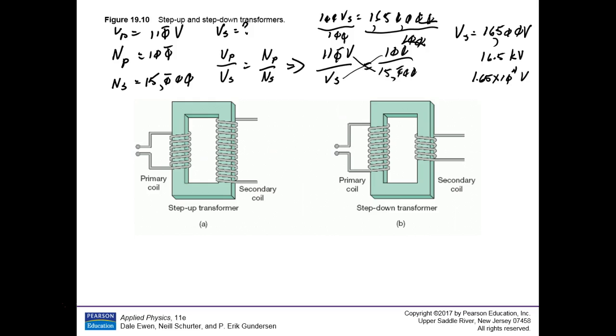Copper losses. These result from resistance in the copper wires in the core, and they're unavoidable. Those coils having 15,000 turns, that's a lot of wire, so there's going to be some line loss there. Remember, the length of the line contributes to the loss. Copper minimizes that, but it still doesn't eliminate it. Magnetic losses, called hysteresis losses, they use that word in medicine too, right? Some energy is lost, turned into heat by reversing the magnetism in the core. That's being reversed at 60 times a second. It's really fast, so it does produce some heat.